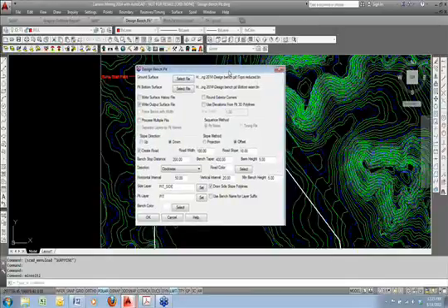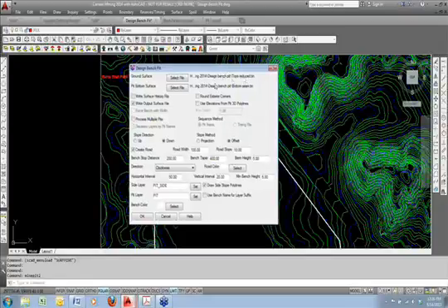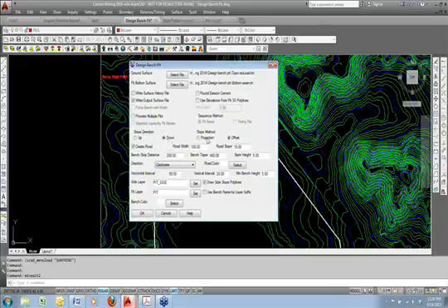in your design bench pit, because when you're cutting these benches and toes and crests and high walls and ramps, a grid tended to round off the corners, whereas this tin is much more accurate and it captures those changing slopes very, very well. And it also then would create an output tin surface. If you start with tins on the input, you're going to get the tin on the output automatically. And you can mix and match too. You could have a tin for your topography, and you could go down to the grid of a seam as an example. All right, so we're going to go down and in.